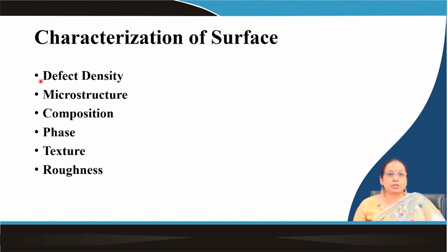So, there are different tools which may be used for understanding or evaluating the defect density, usually non-destructive testing based tools, or X-ray micro CT scanning or gamma ray scanning. Those techniques, for example magnetic particle inspection testing, then ultrasonic testing, are all applied for knowing the defect density of the component, which are present on the surface or maybe in the subsurface region, which greatly influences the surface property as well as the